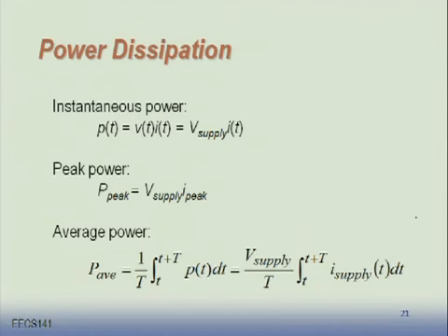Have you heard of what are the different types? So there is maximum design power. There is some other type of power that is larger than that maximum power. Have you heard of power viruses? Power viruses. Okay, so maximum design power is what the design team designs for: practically the shortest loop, the worst case loop that is going to exercise that processor the most.